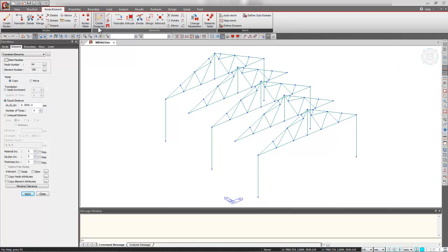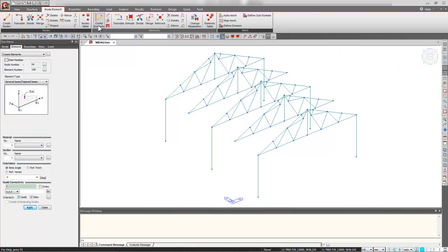and then further I can create some beams by using the create elements command. In this command, the good part is that by clicking on one node and the last node, the nodes lying in between will divide the line element that we just created. So no need to worry about the intersection of the elements. So similarly, I'll create the beams, even the ridge beam.